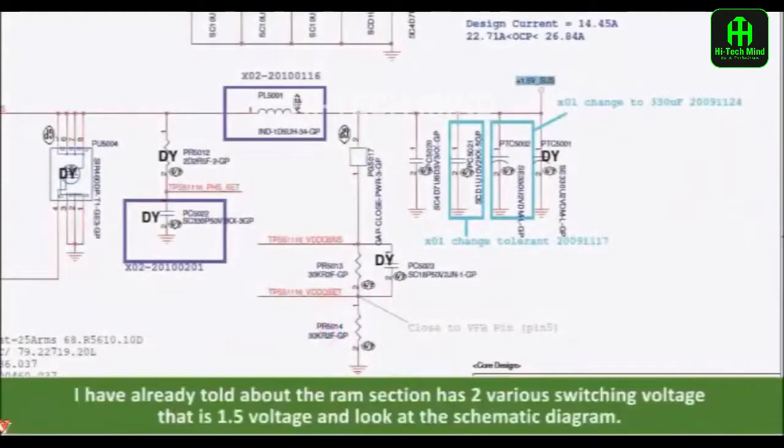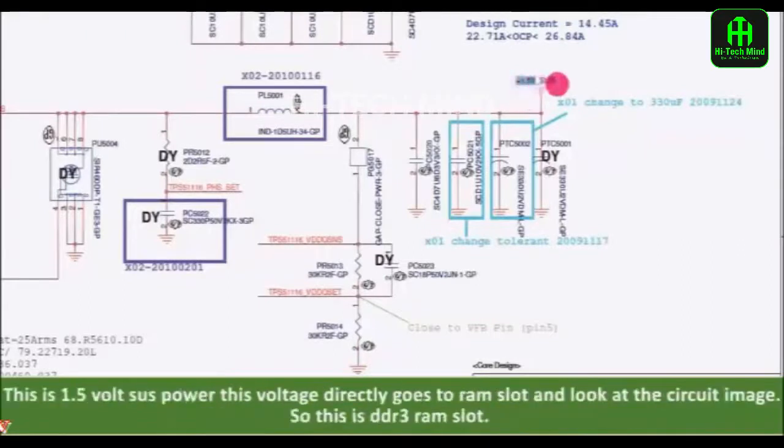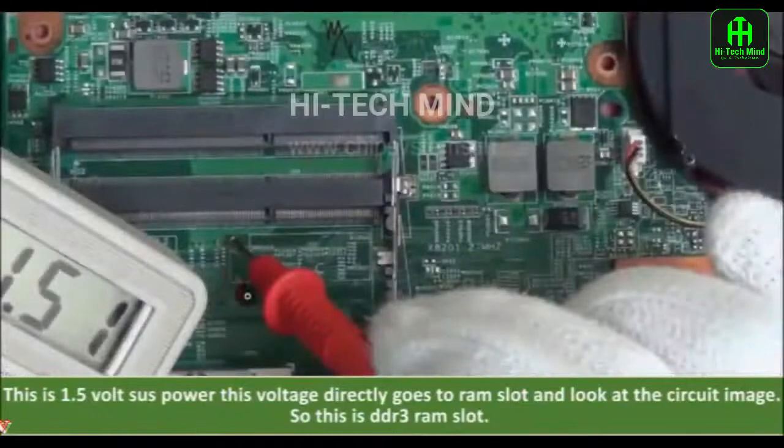I have already told about the RAM section. It has two switching voltages, one of which is 1.5 volt. Look at the schematic diagram. This is the 1.5 volt source power, and this voltage directly goes to the RAM slot.